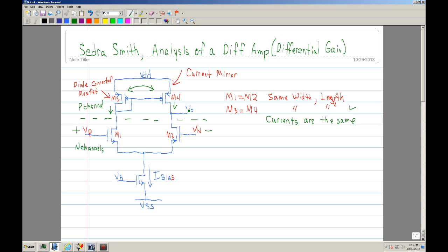That's at the output. So with a positive, you get a negative here. That means that's the wrong polarity. It's not a positive node, it's a negative node. Now if you come over here and do the same thing, you start with a positive, you're going to have an inversion, so you get a negative through here, and then you have another inversion, so it's positive. Since you start with a positive and end with a positive, this is your positive node.